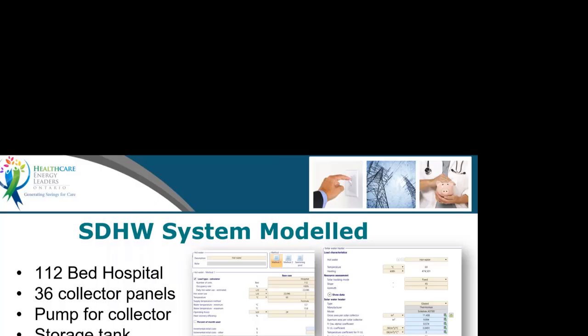But to your point there, Michelle, certainly within RETScreen, if we look at the screen here, the way we model this is we model the hot water load itself to begin with. And then we take the residual load after any measures, which could include heat recovery. So RETScreen is built to be able to do this. And then we model the solar side of it, which is the screen on the right. So again, sometimes having the right tools that make it convenient to do the right things makes it easier to look at these types of designs.